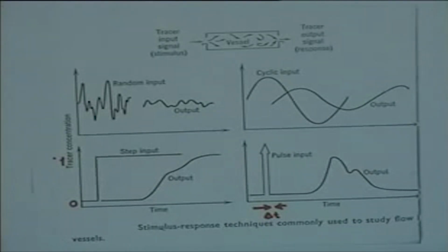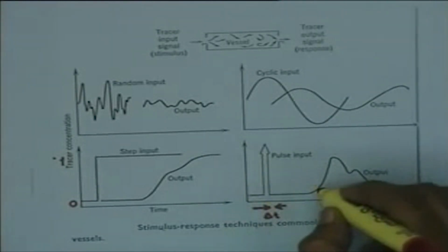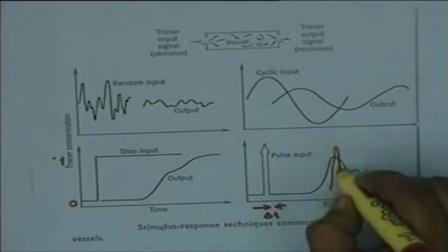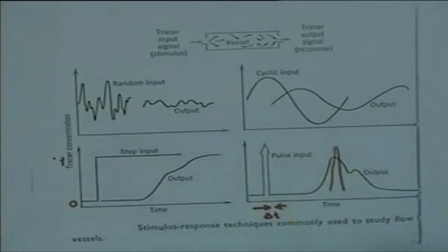Essentially the theoretical chromatographic column, adsorption column, must operate as a plug flow reactor, with plug flow behavior. But ultimately, because of certain non-ideality, there is some kind of broadening. That means the fraction which you are interested in gets distributed over a period of time. Ideally it should come out in a very short period of time, but it comes out in a broadened fashion.